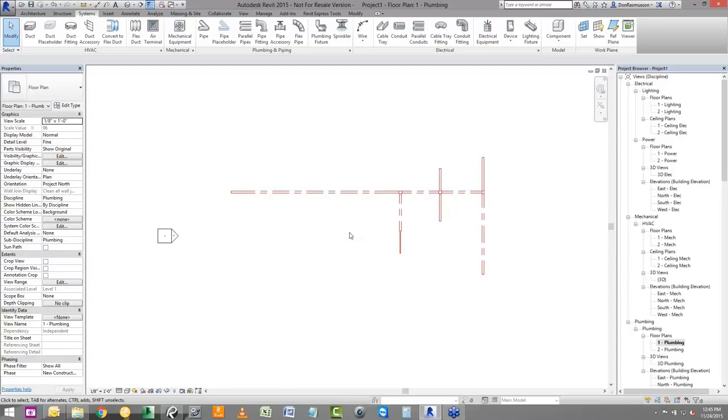If you don't set up your pipes and your pipe types or your ducts and duct types and duct systems for that matter, the analytics aren't going to work very well. You can get down as far as coefficients for head pressure on fittings. As a percentage of the amount of clients we work with, I'd say that it's a relatively small percentage because very few clients actually take it this far and get this all set up.